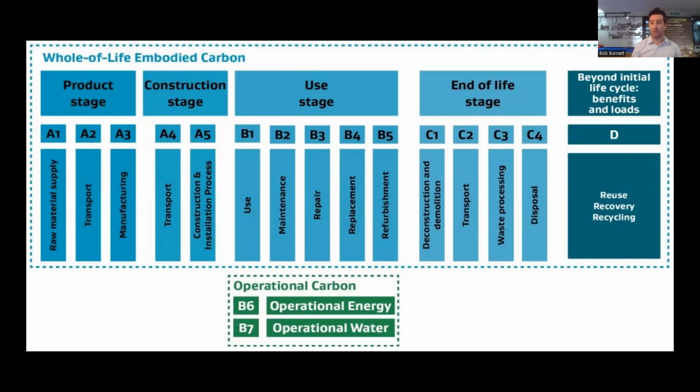An interesting point of interest on that: if you were to look at maybe a drywall product or a timber product produced in New Zealand versus the same product manufactured in Australia, you will find that the Australian product often has about 4 times the carbon level. Now, most people would think, yeah, sure it does. We've got to put it on a boat and transport it over. That's where the extra carbon comes from. Not quite the case. It's actually because there's a very high reliance on coal-generated electricity in the grid in Australia, where there's a high level of renewables in New Zealand. So that creates a huge disparity between those materials. So something to keep in mind is that it's not just distance from where your materials come from, it's actually the electrical grid that country operates.